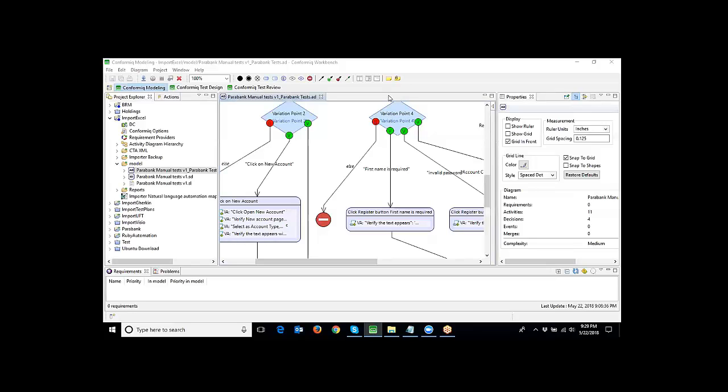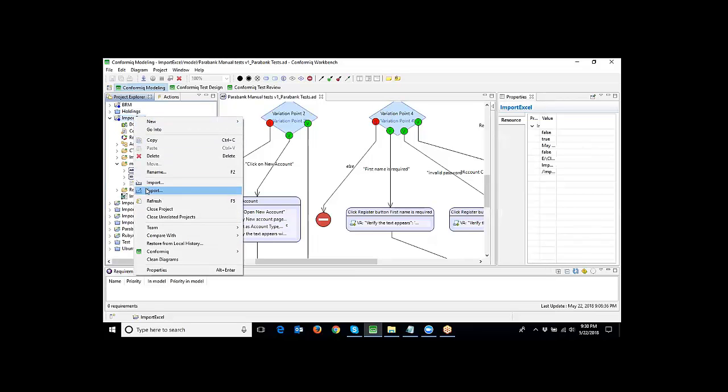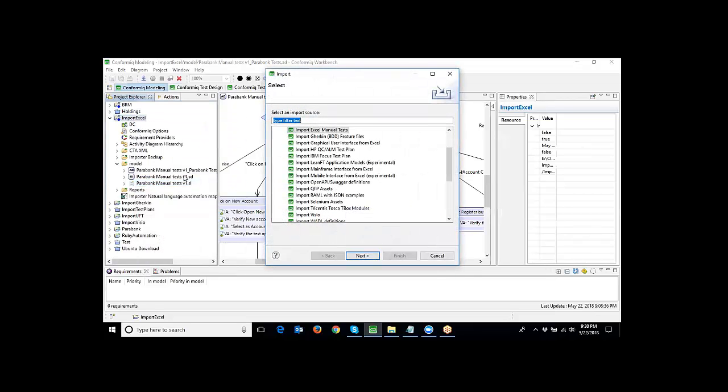How can you handle multi-user edit of the models? Yes, the tool can be integrated with Git. So if you can see here, there is an option where you can import the project directly from Git itself. If Git is completely configured, the base model can be exported and integrated with Git, and the different users who have access to the Git environment can access the model directly from Git, and that can be imported to a local repository.